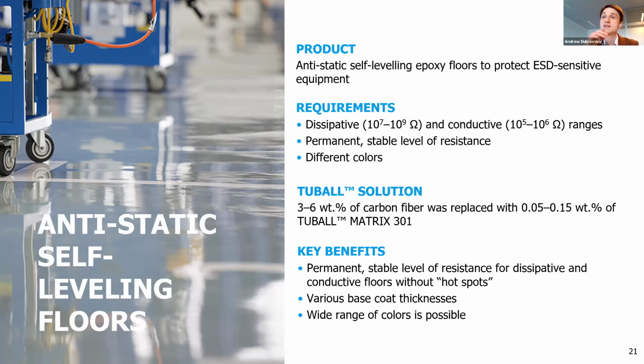And we have seen that surface to surface resistance is extremely good. It was something like 10 to 6 or 10 to 7 ohm, two-point method of measurement. So everybody was happy. But when we tested surface to ground resistance between the surface and the copper tape, the grounding, the system was completely insulative.